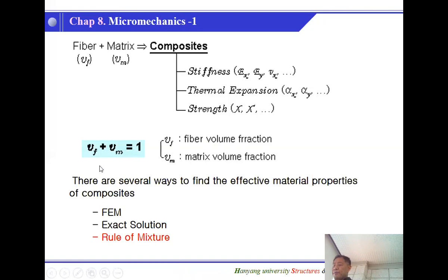And these fiber volume fractions are very important numbers. And of course, these are fractions, okay? Fractions, meaning that the sum of the fiber volume fraction and the matrix volume fraction should be 1. And sometimes there is a void.